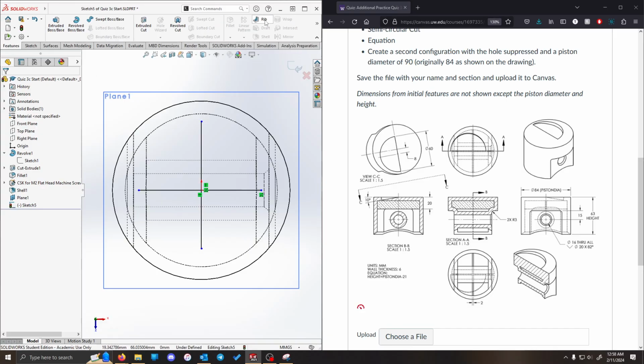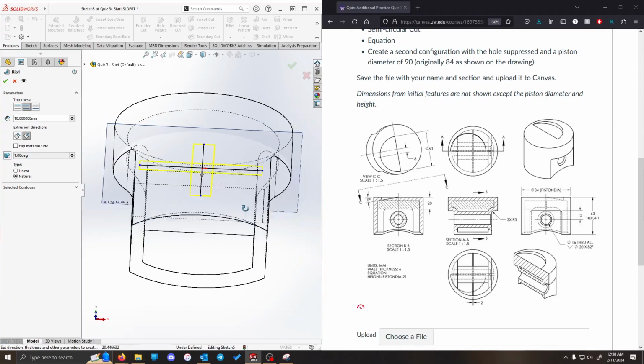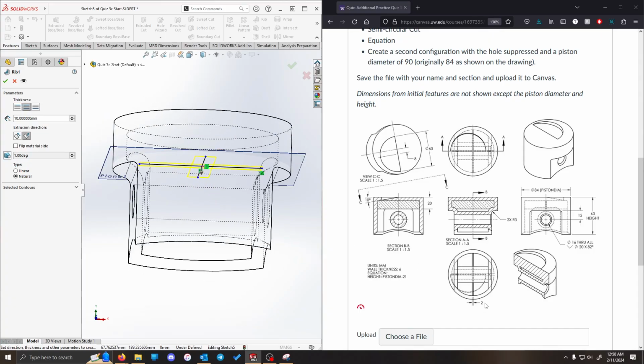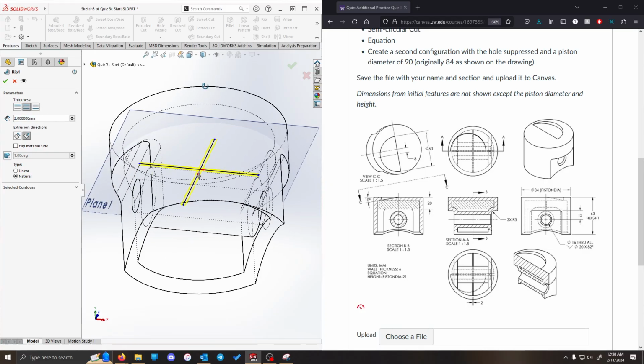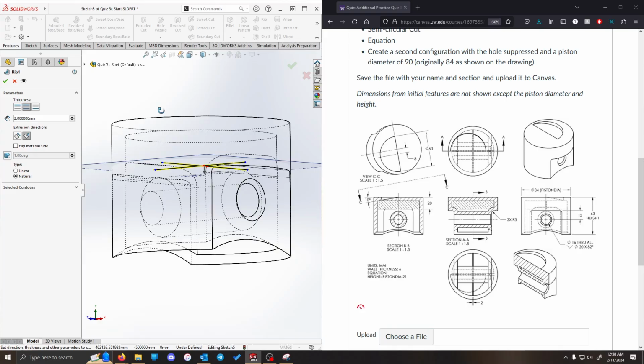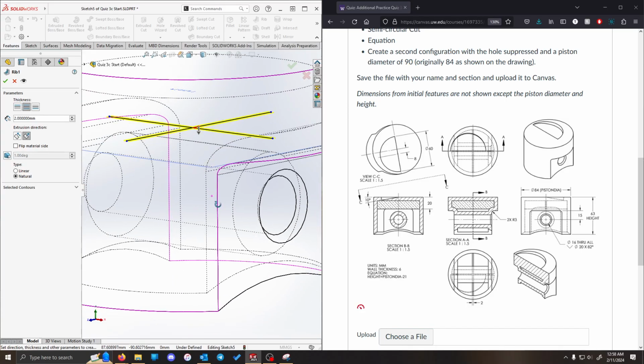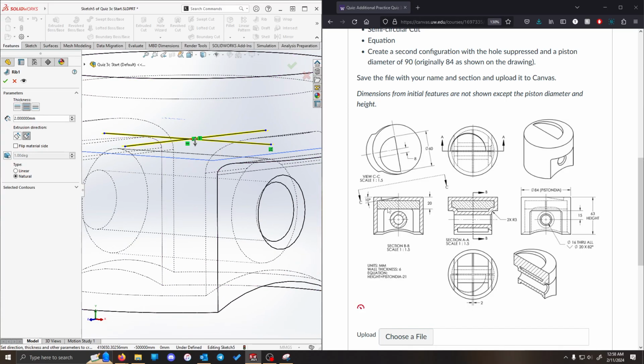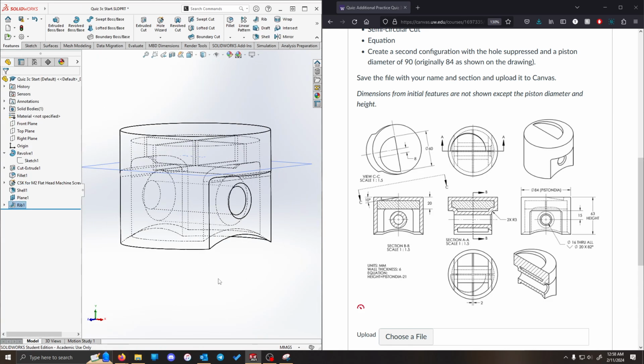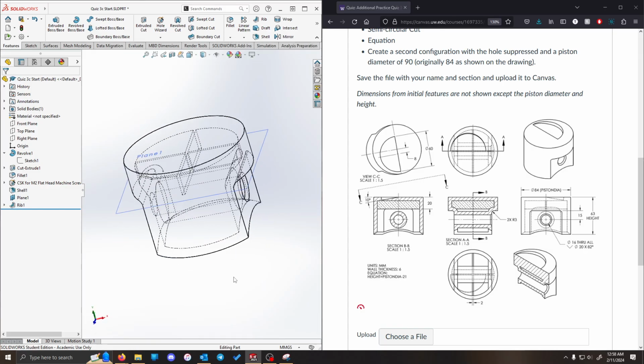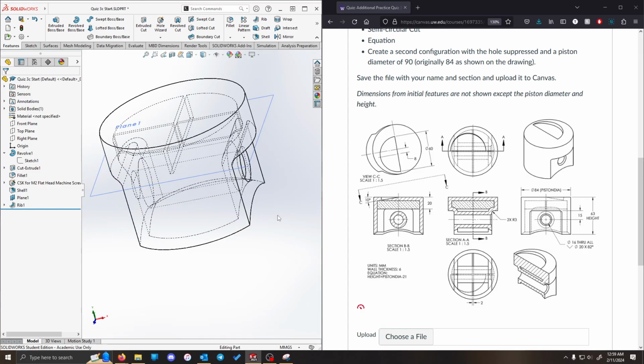I'll pop back over to the Features tab. We'll go to our rib, and we can also see in our bottom view that we have a rib thickness of 2 units. All right, new problem. Our arrow is pointing the wrong way. So we can see in our drawing that we have the material going up. So we need the arrow pointing upwards. So I'm going to check our flip material side, hit our check mark, and that fills in our rib for us. Nice.